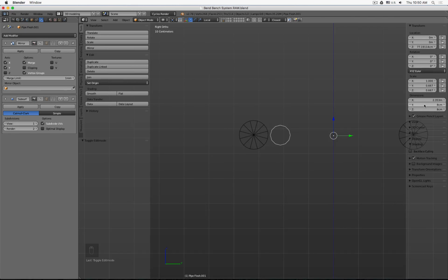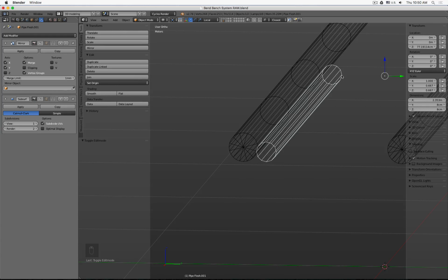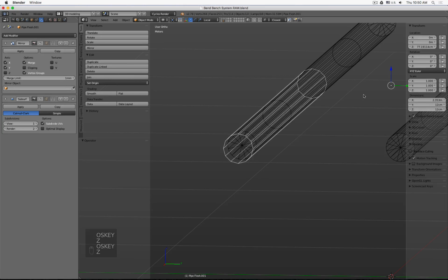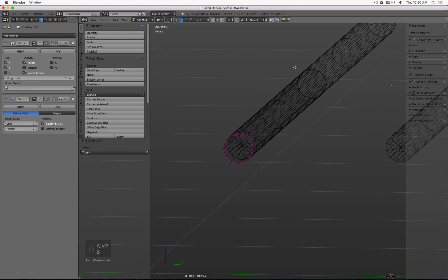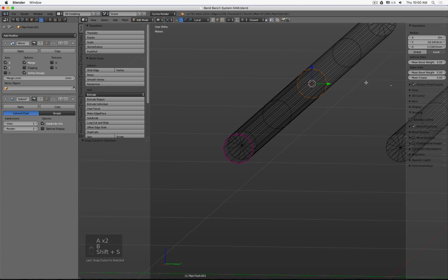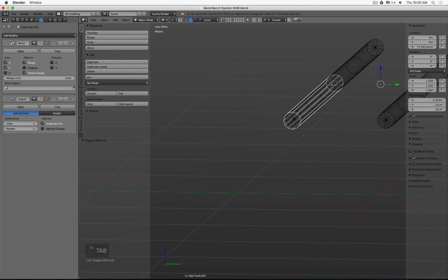And you noticed, yikes. The scaling works, but actually it moves its direction. So that's not really very good. And that is because we used this small trick that actually our object center point is at the world center point. So if we want to just scale the pipe where it is, unfortunately in this case we would have to re-center the object center point to the center of the pipe.